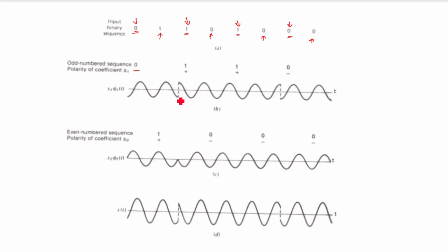Okay, right. And similarly here for the symbol 1, the lower one is having the carrier sine 2 pi fct, right? So it will start as a sine 2 pi fct multiplied by the amplitude which is positive, and it will give you the sinusoidal signal here. Now this is the sampling interval, the interval of the QPSK symbol, I can say, right? This is the interval for a BPSK symbol, and these two symbols together will have an interval T, the time duration T. It is the QPSK symbol duration, right?